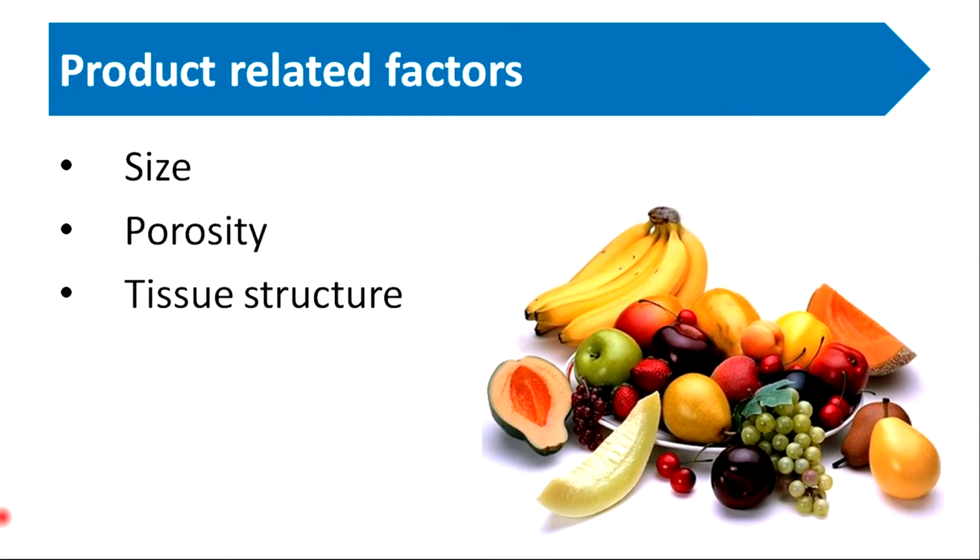The shape of the solid material is an important factor because the moisture loss and solids gain decrease with an increase in sample size. If the solid is bigger in size, it will dehydrate more slowly because the length of the diffusion path is greater and less surface area is available for solid exchange. Hence, the solute will enter the sample at a slower rate.